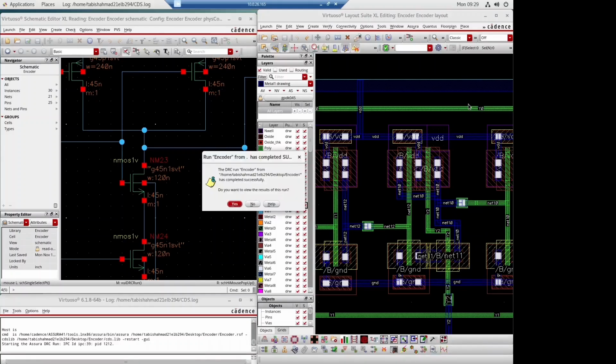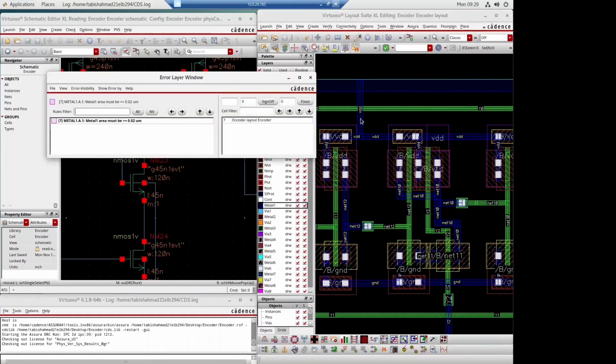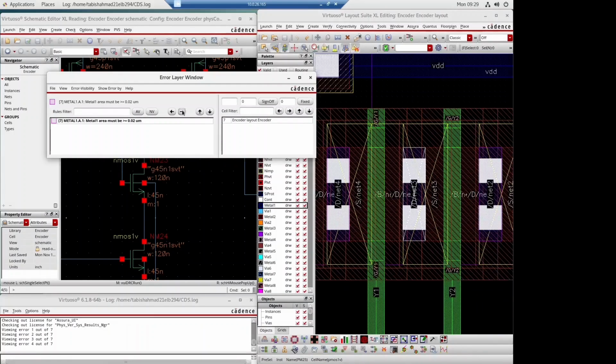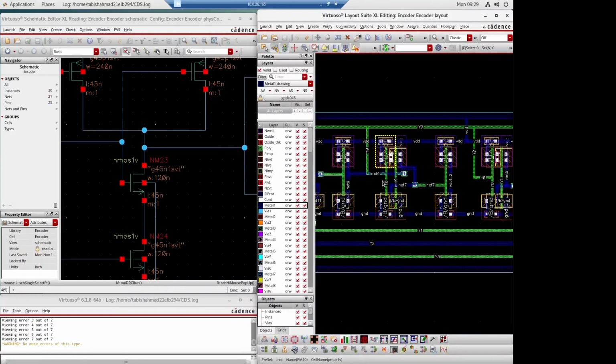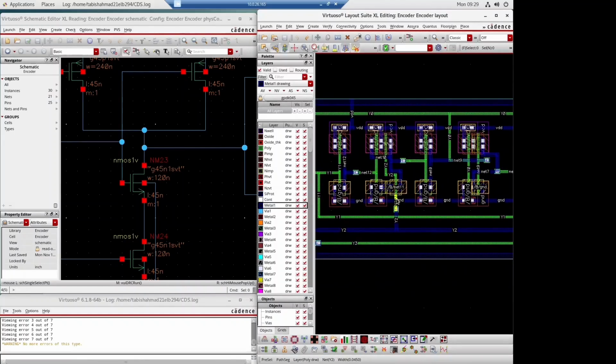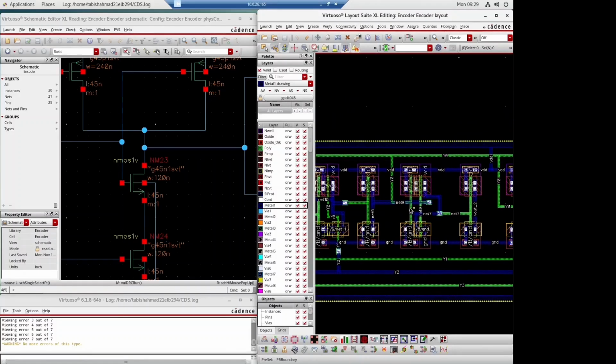Yes. Let it complete. Okay, great. So we have removed that overlapping error. Instead of 8, we are getting now 7. So the remaining parts where the cross is coming, we have to do the same exercise on each part. Now you can see that we are getting this error in this PMOS part above this NMOS, this one.